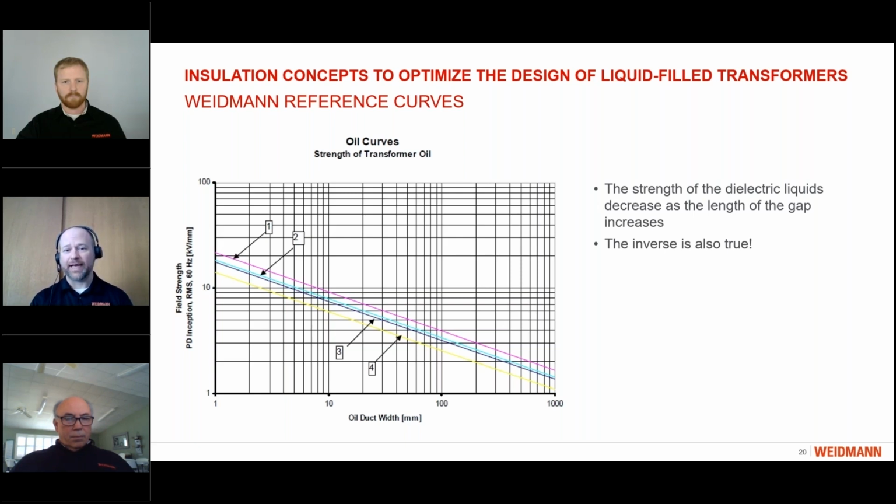You can see, however, as the duct is increased in length, that the strength decreases. What's important to note is that the inverse of that is true. The smaller the duct, the stronger the gap dielectric strength is for PD inception. PD meaning partial discharge. Next slide, please.